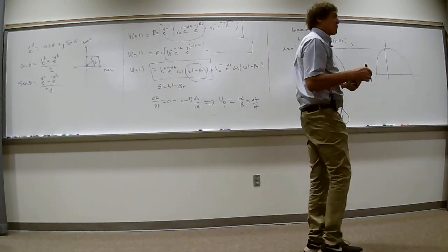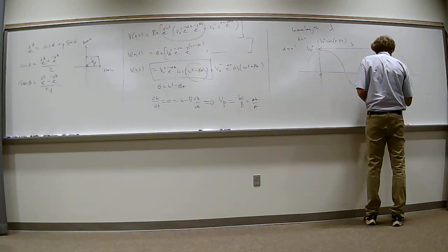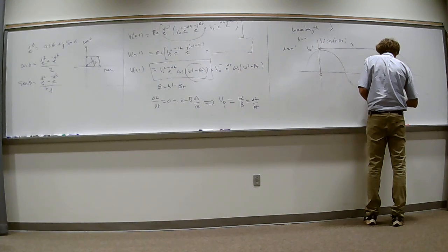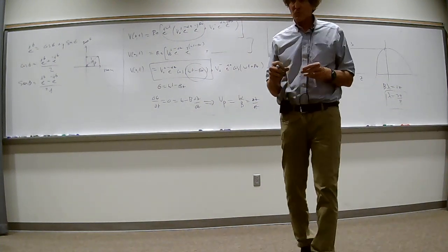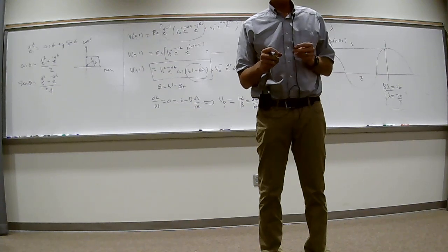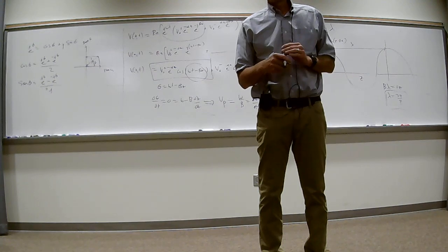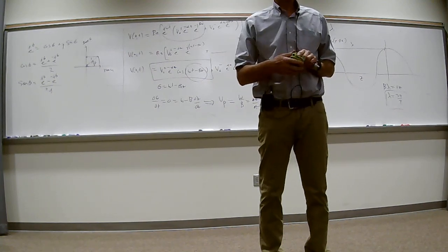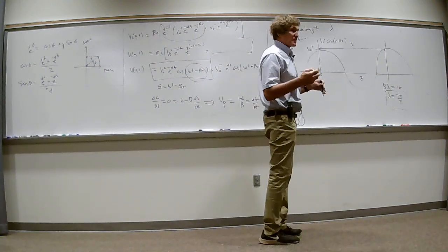Now, that's the point where the wavelength is defined. So here, we're going to have beta times z, where z is the wavelength, equal to 2 pi, or the wavelength itself is simply 2 pi over beta. And that's the fundamental definition of wavelength. Do y'all follow me on the reason for it? We got phase velocity, we got wavelength, both critical. Everybody with me on this? And when you work problems, this will become very clear to you, because then it reinforces what you've heard. You force yourself to make sure you understand the theory.